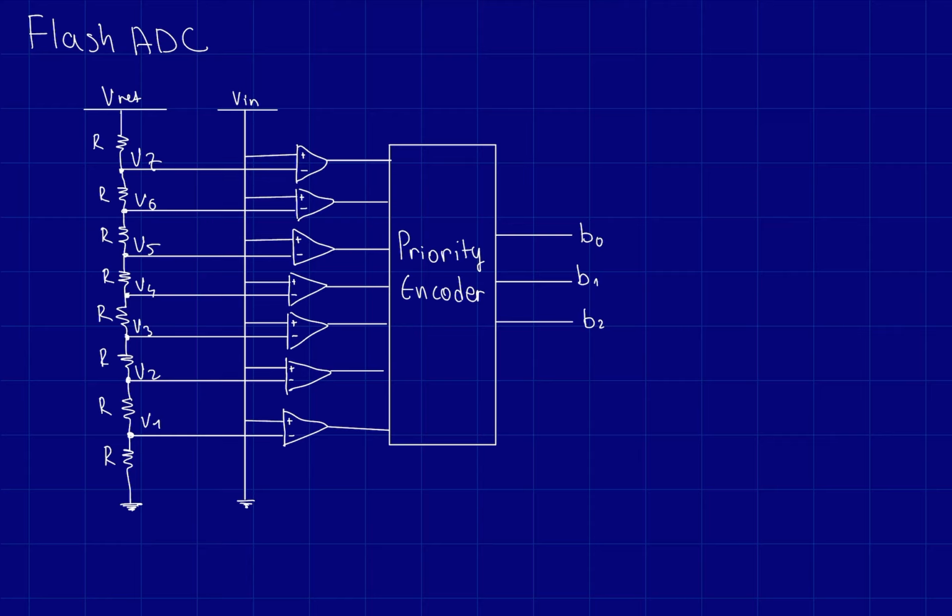To remind you from the previous video when I was introducing analog to digital converters, when we wanted to see how many voltage levels we can have with a certain number of digits, we used this formula: 2 to the number of bits equals the number of voltages.